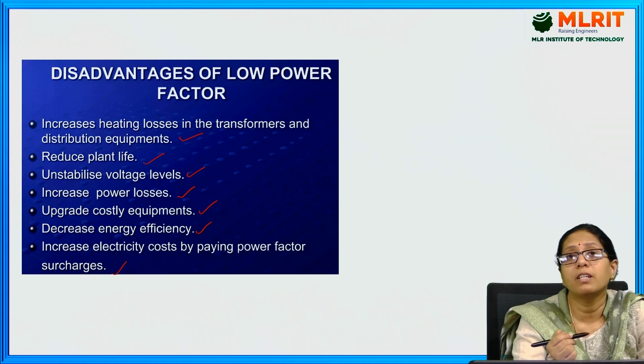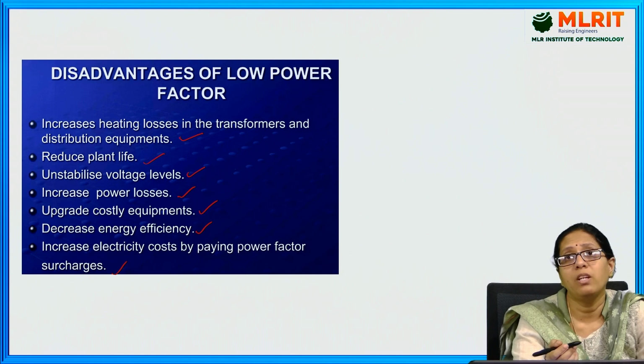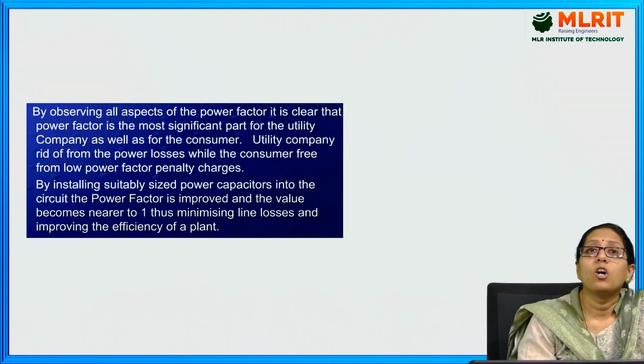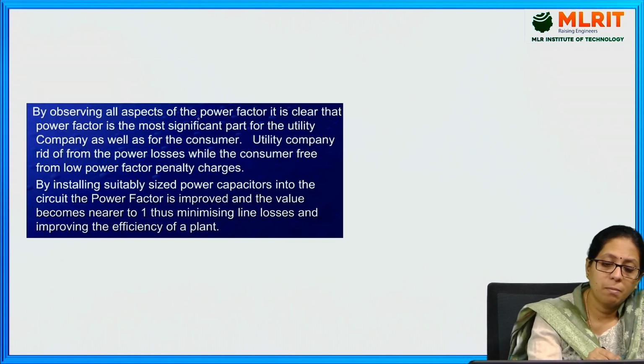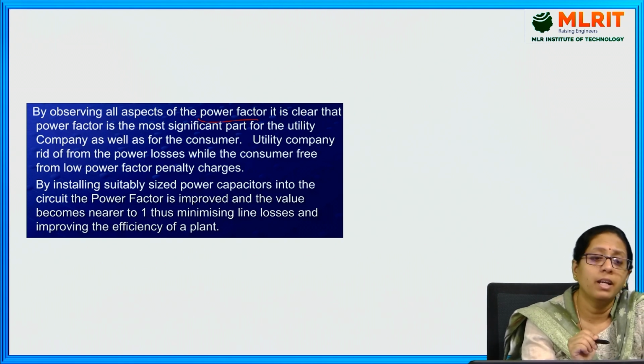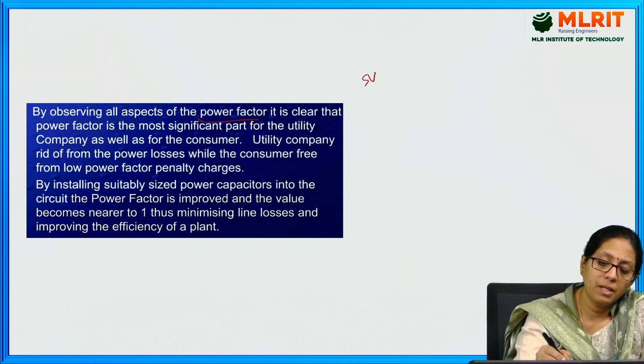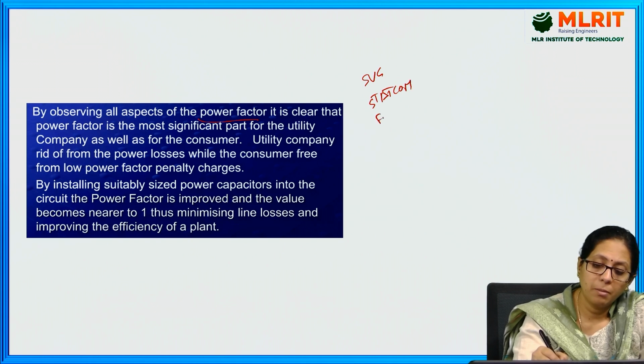So the power factor has to be improved or increased, or it should be almost equal to 1 or unity. By observing all these aspects, the power factor should be almost equal to unity and should be improved by using different kinds of techniques, like it may be SVC or it may be a STATCOM or it may be a fixed capacitor or switched capacitor